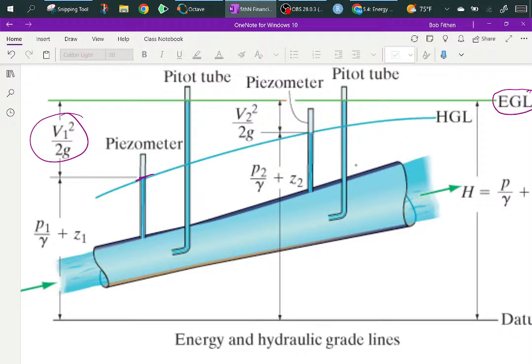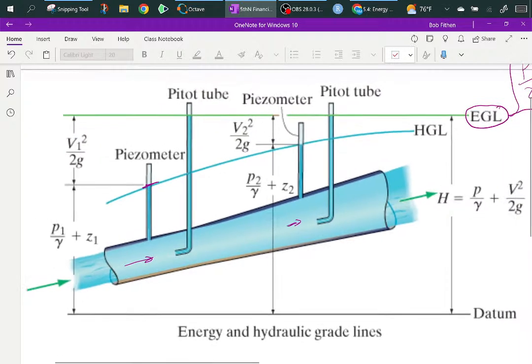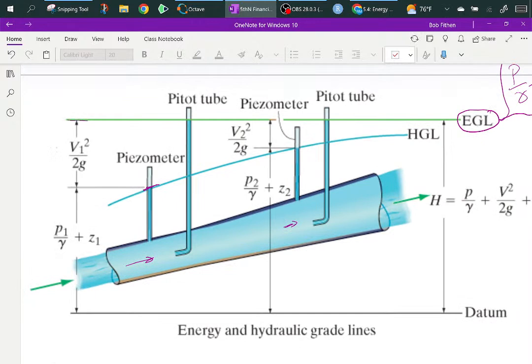And then what happens is you go uphill a little bit, and he shows it kind of widening the pipe. And this reduces because you widen the pipe and the flow went from this speed to that speed. And then you do the same thing, you ram it against there, and you should get that same level. But if it's a long enough piece of pipe and you're looking at a real situation, your energy line, you're losing a little energy as you go.